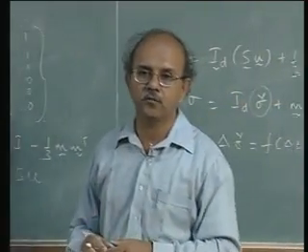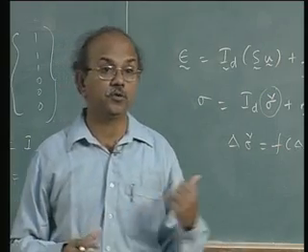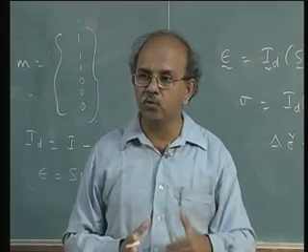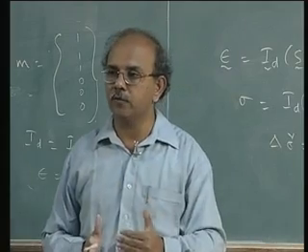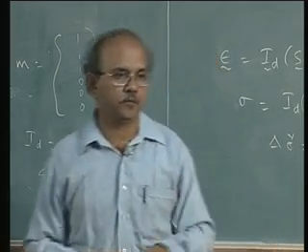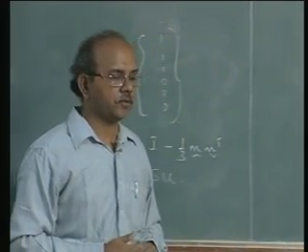For any other constitutive equation where incompressibility is an issue, you can use this. But we are still in the small strain regime, so you cannot use this formulation for large deformation. You have to make some amends if you want to use it for large deformation.